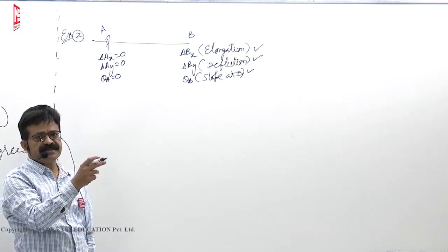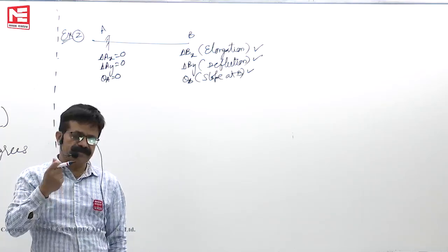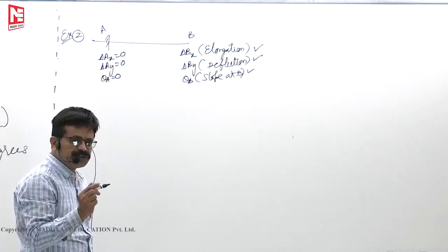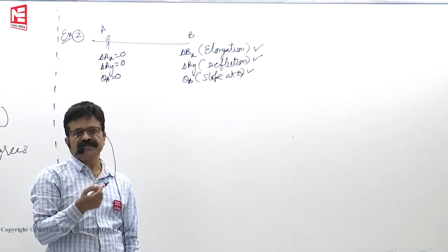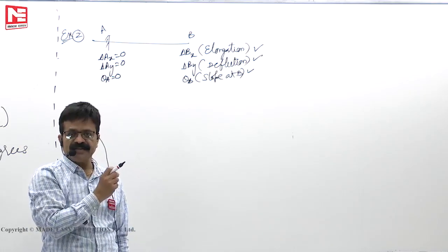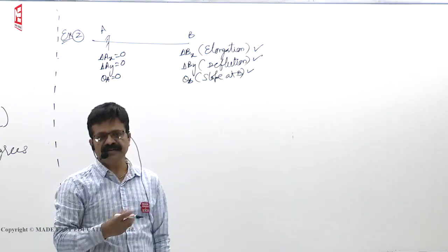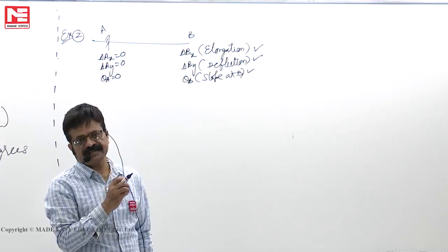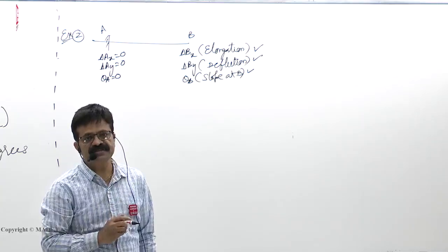So, generally beams means a flexurally loaded member, with either very small value of axial force or sometimes 0. If you are sure that axial force is 0, then elongation is 0. Then accordingly in the exam they will give you, if you assume that they are inextensible members or axially rigid members, you will assume inextensible members if there is no load at all, that means they are not elongating. But if very small load is there, if you want to neglect the axial deformation, then also we can take it as axially rigid, then deformation is 0.